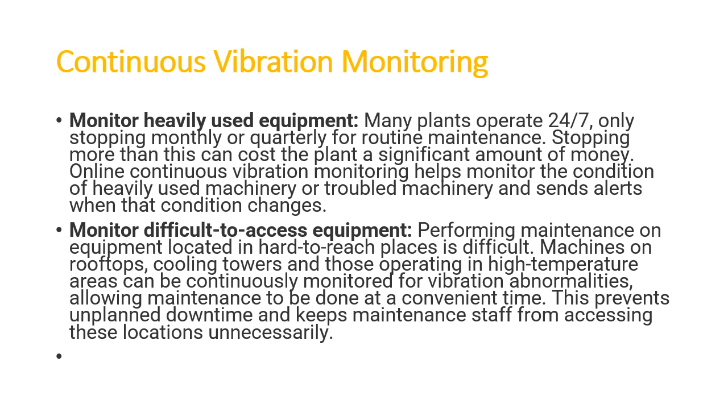And if a fault in that machine can cause havoc, a huge amount of money and loss of reputation, all these things can occur. So in that kind of machine, you need continuous vibration monitoring. In continuous vibration monitoring, multiple proximity sensors or accelerometers are installed on the gearbox, on the driving end, on the non-driving end, and that data comes directly to the DCS panel or the SCADA system, where you can see the data.